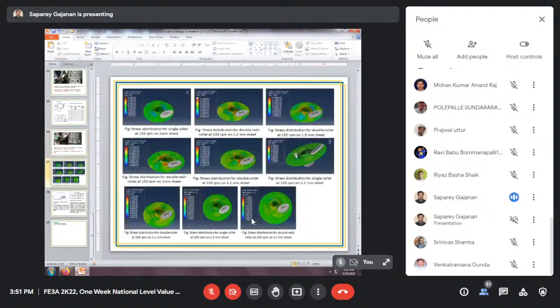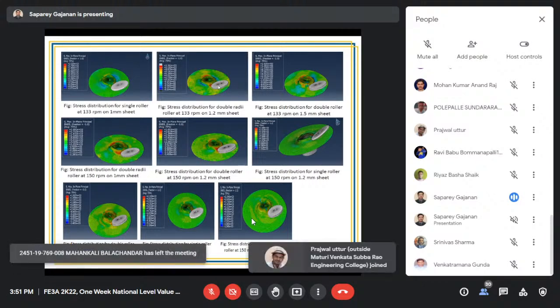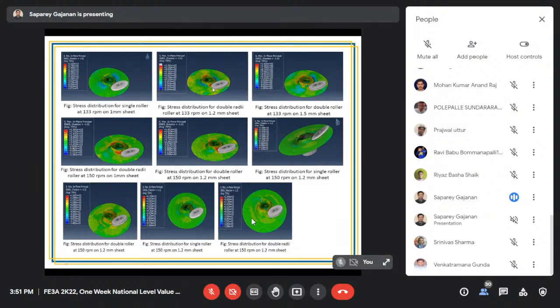These are the components obtained from the parabolic. Yeah. We have simulated the same thing using ABAQUS. So you can see the deformation in ABAQUS. You can find out where the weak points are, where more stress has been generated, how the failures can be obtained, how to control the flow direction of the roller, and also what parameters, such as speed, have to be increased or decreased. All that information can be obtained by looking at the stresses that have been developed.